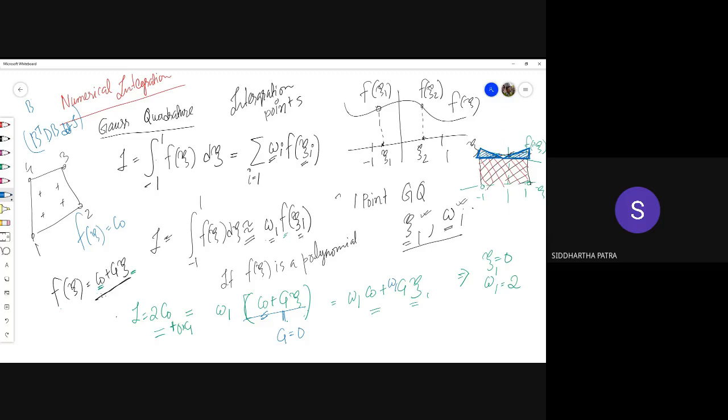And the location of the single point Gauss quadrature should be xi equals 0.5 and eta equals 0.5. Why 0.5? Because for a CST element xi ranges from 0 to 1 and not -1 to 1, so you need to adjust the scale accordingly. Because it is a constant, for a CST element you don't have to do the numerical integration at all, but for the proof of concept we can say that if we need a single point Gauss quadrature, it should be at xi equals 0.5 and eta equals 0.5. Actually because this term is constant, it will be constant everywhere.